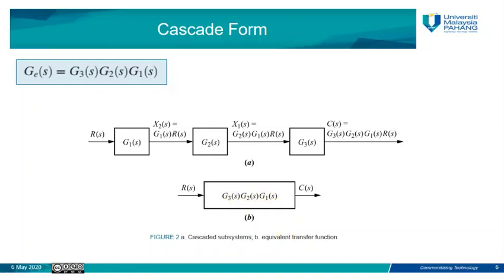In the future, if you have any type of cascade form in your complicated system, you need to merge these subsystems into one single block or one single transfer function.